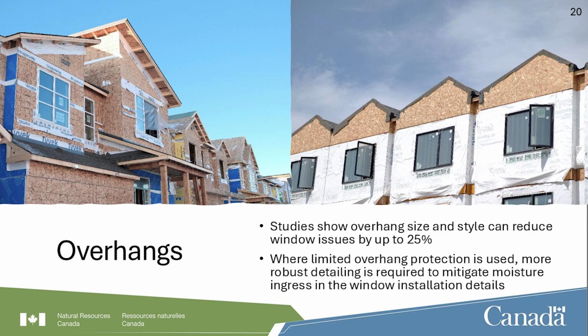Do you see a potential failure here in this assembly? So the framers put the house wrap on, they put the windows in. What if the siding guy doesn't get correct overlap from here over this house wrap? You got an entry point. What if up here, because this is a peel and stick, it's secured to here, so the siding guy goes, the heck with it. He just brings his house wrap over top of that. And now everything gets directed in behind there, and everything's behind and into the rough opening, down in the wall.